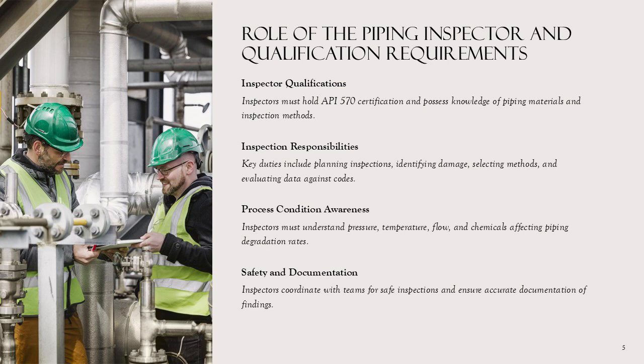Beyond technical knowledge, inspectors are expected to exercise sound engineering judgment, especially when evaluating anomalies, corrosion trends, or unexpected damage. They must coordinate closely with operations, maintenance, and engineering teams to ensure inspections are conducted safely and efficiently, particularly during on-stream activities where systems remain in service. Documentation is another critical responsibility. Inspectors must ensure that inspection findings, thickness measurements, corrosion rates, and recommendations are accurately recorded and maintained in auditable records.